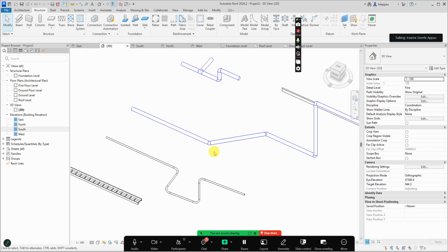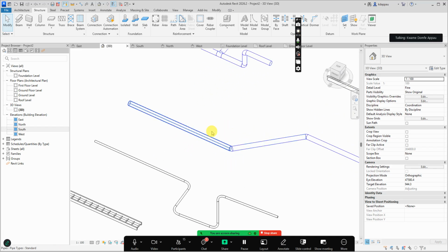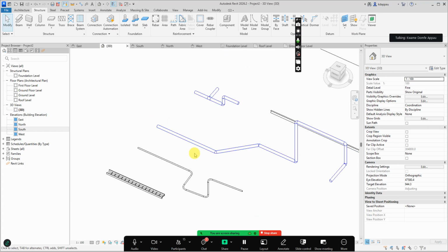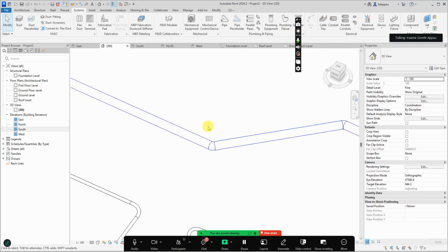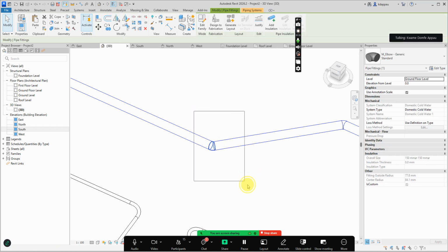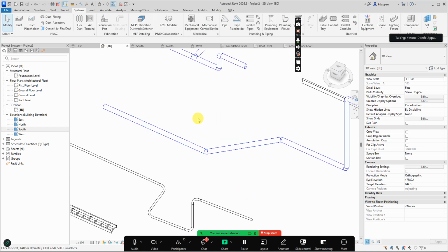But there's one thing about system objects, that is the ducts, the pipes, and then the cable trays. There's something called fittings routing. You look at the fittings routing later on. If you don't do the routing settings correct, anytime you try to draw these pipes, you get issues.